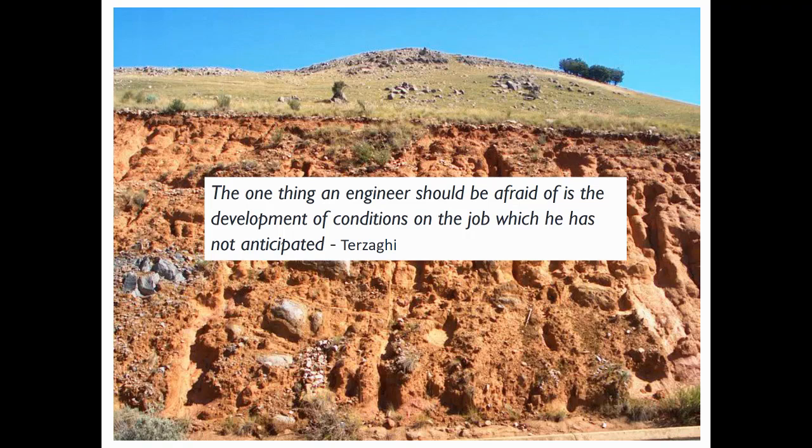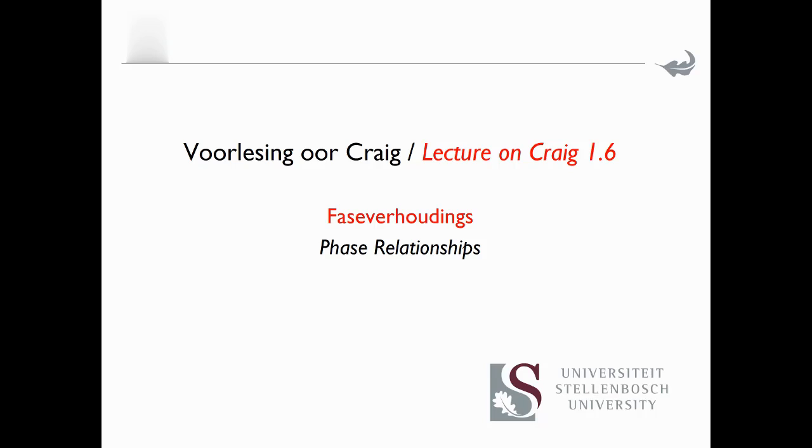If you look at the picture with the grass on top, you might think those are solid bedrock outcrop, but the soil profile clearly shows that you have a very deep developed soil profile. So if this was not anticipated up front, you could have serious problems when you go to the field.